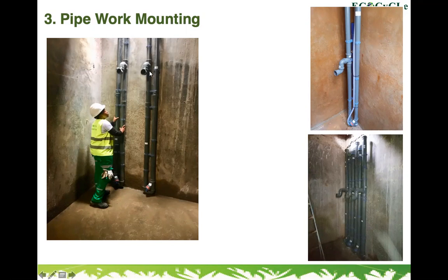Yeah, that one is an elbow. Now, the water usually gets filled to up to that elbow, up to some levels above the elbow, according to how the design is made. And then any clear water that is above that discharge elbow gets into the treated water tank after some time.